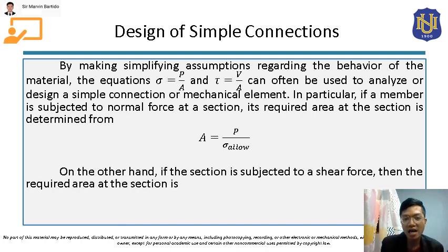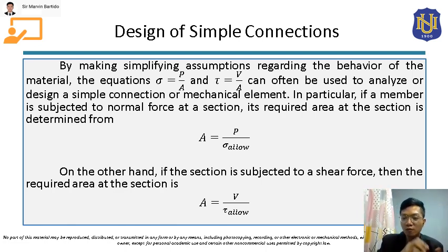On the other hand, if the section is subjected to a shear force, then the required area at the section is equal to the shear force V at that section over the allowable shear stress. Through this, we can solve for the area and then the required diameter, required thickness, or anything that we need in the design of that connection.